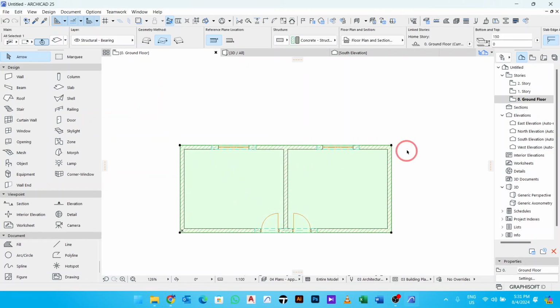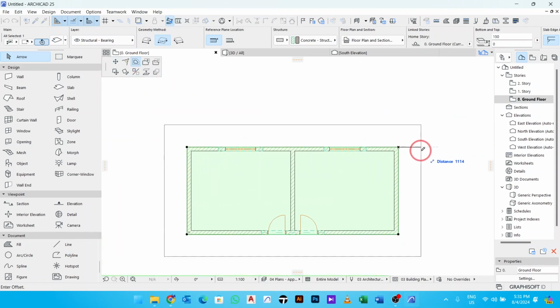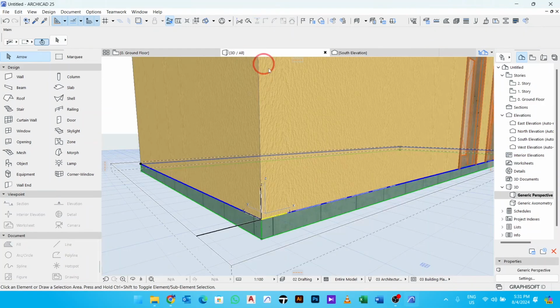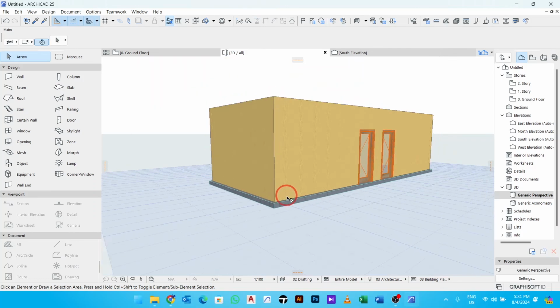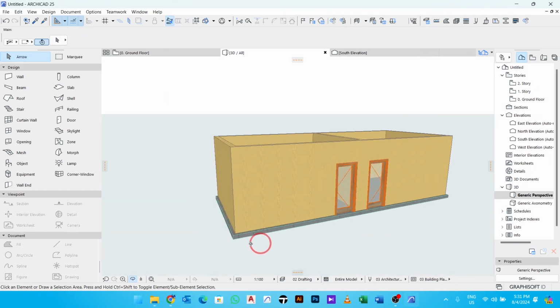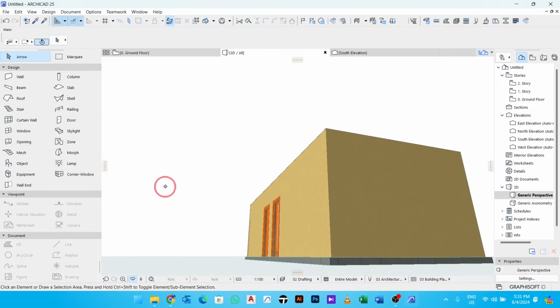You select the slab, you click at one of the node, and then from this pet palette, you click, and then you give it outside direction, something of 100. As you can see, the slab is already being extruded all over by 100. So you can press O for orbit to look around. So this is a concrete slab.